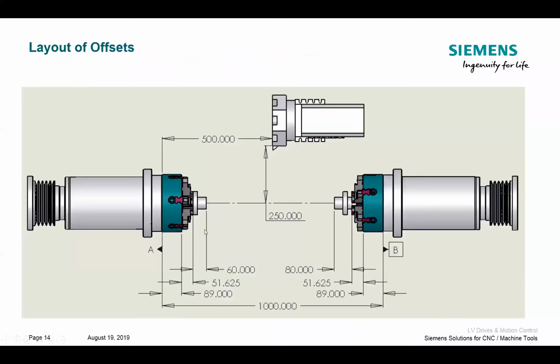So when I first lay it out, I really want to think about my nesting, because it's real important once I introduce the counter spindle and I go to grab it and I want to pick and place things, knowing where the part is in space. So remember, my datum is the back spindle face. So I have a couple constants I have to deal with. I have a chuck body thickness, I have a jaw projection, and then I'm going to have some kind of desired projection of my part to accommodate enough room to machine it without driving my tool into my chuck.